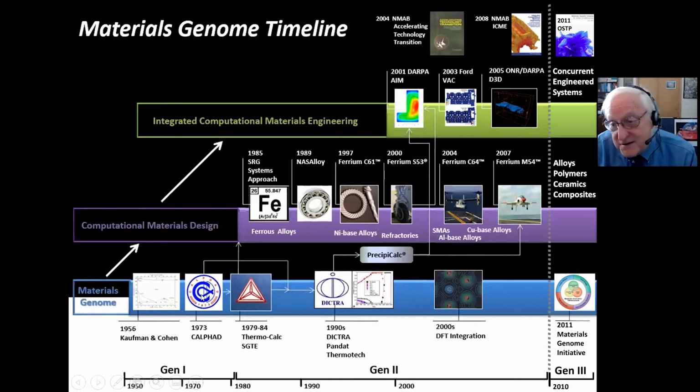Becoming an international organization in the 1970s and expanding beyond solution thermodynamics to molar volumes, atomic mobilities to solve dynamic problems, and even now elastic properties. Historically, all empirical measured data, deduced from phase diagrams primarily, but with the improved accuracy of DFT methods, first principles energy calculations are now a significant contributor to that overall process.